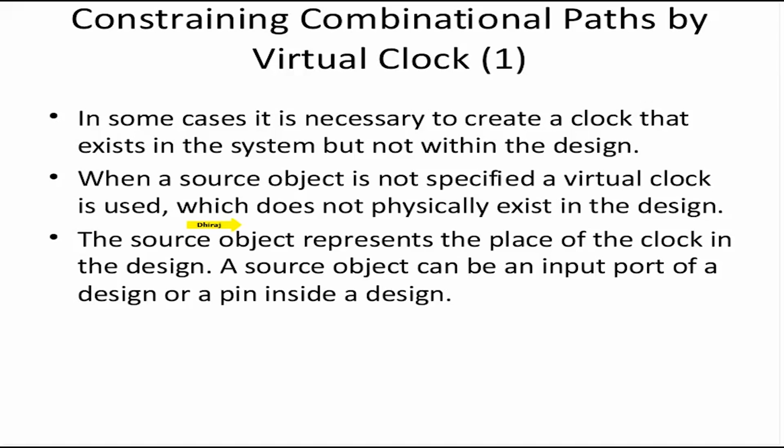But now, if the clock is not actually part of the design, there will not be any port associated with it. So if you give this command without the port, Design Compiler will create a clock and call it a virtual clock. Virtual means it does not have any real source. So when a source object is not specified, a virtual clock is used, which does not physically exist in the design.